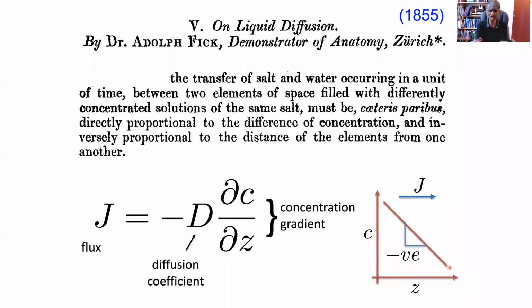So this is the classic Fick's law of diffusion. I want you to note very carefully that this is a constant. It doesn't depend on the magnitude of the gradient here. So it's a proportionality constant, and the effect of the gradient simply comes in through this term.